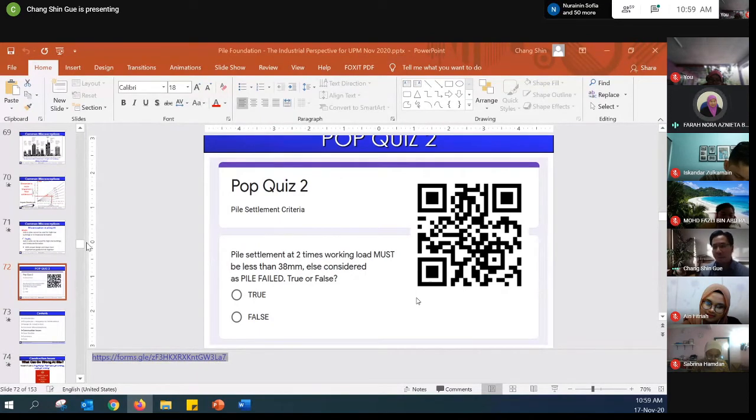Okay. And then since the casing cannot go in, there is a possibility that when you pour in concrete, the concrete goes out of that area without the casing, isn't it? You mean if you're using bored piles, whether the concrete will actually go out? Is it possible? Some possible, especially when you have a cavity.